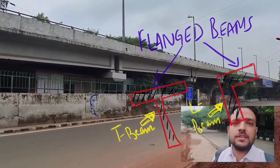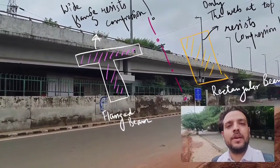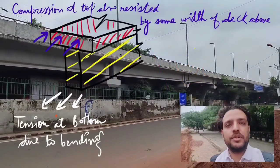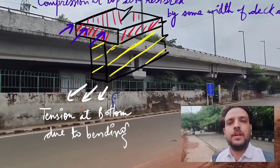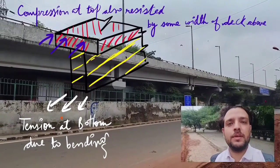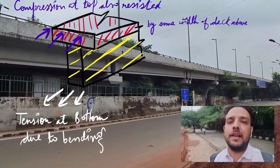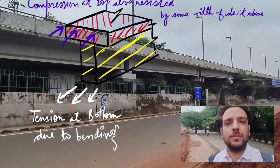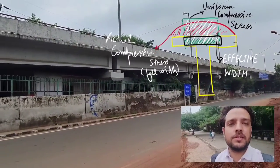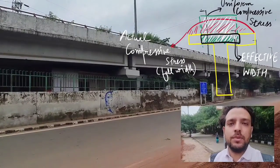Notice through this sketch that in a flanged beam the deck above also helps in resisting compressive stresses, because the portion of the deck near the web resists more compressive forces than the portion away from the web, and hence a concept of effective width is introduced in designing flanged beams, which is missing in rectangular beams. It means more of the structure is contributing in resisting forces, and hence the utility ratio of the structure is higher than a rectangular beam.